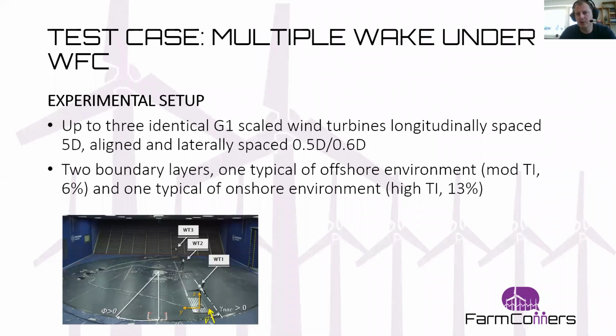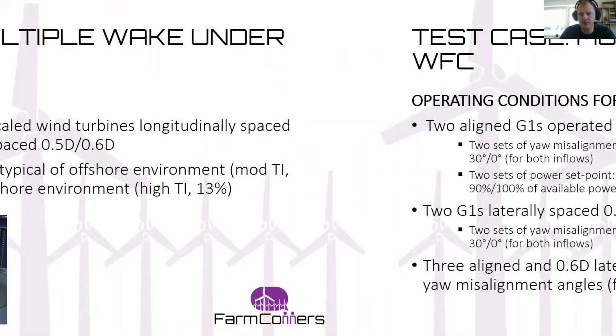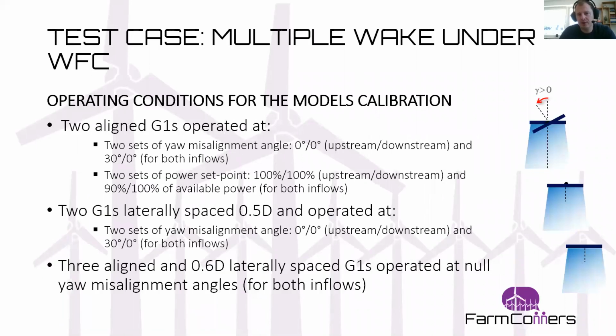Finally, for the multiple wake case, it's quite interesting. Again, the setup here: we were using up to 3 G1s, longitudinally spaced 5D and laterally spaced aligned, and also laterally spaced 0.5 and 0.6D. Again, 2 inflows as before. And for the model's calibration, quite a few operating conditions are available.